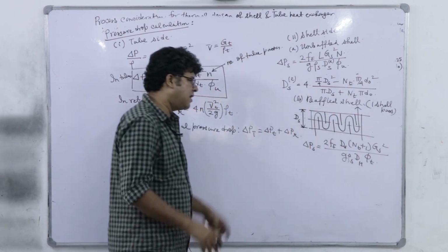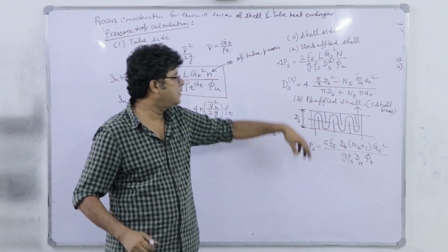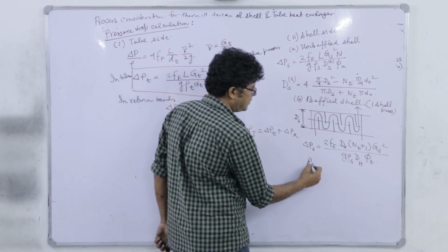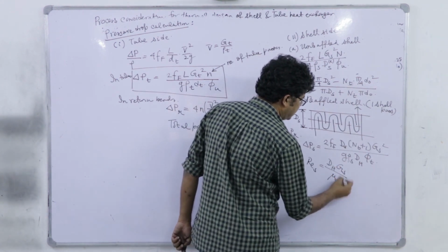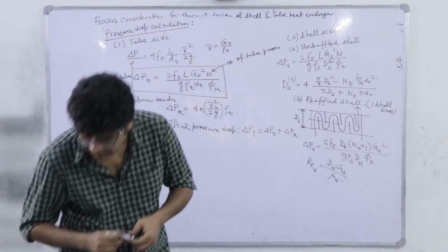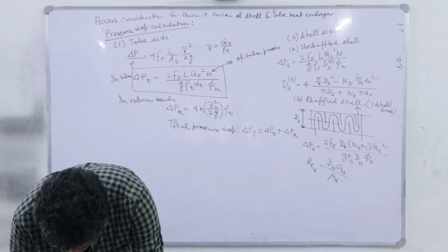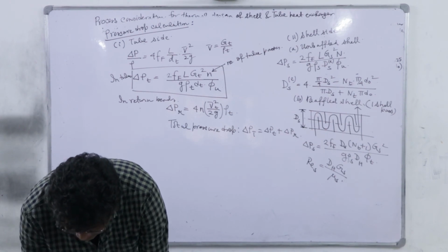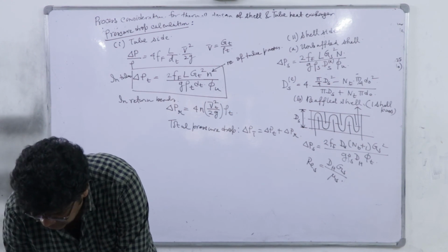right. So there are empirical charts by which we can calculate the friction factor f_f. So f_f we can calculate from the Reynolds number, Re shell, which is d_H into G_s divided by mu_s. So once we get this, d_H has been already calculated, we have discussed it, and d_H is the hydraulic diameter of the shell. The same equation which we have solved for square pitch and triangular pitch will be used here, and from there we can calculate the shell side pressure drop.